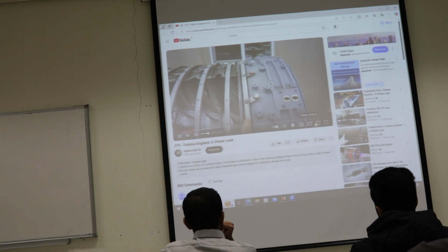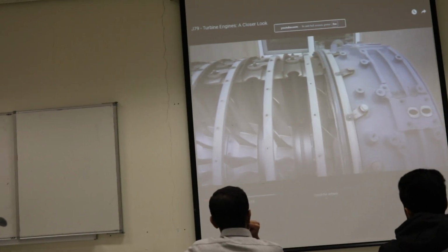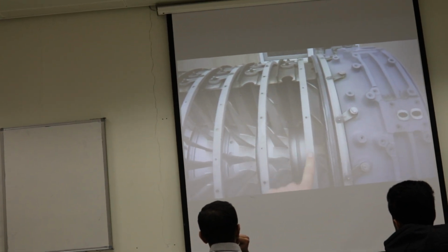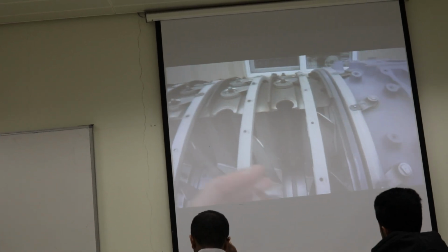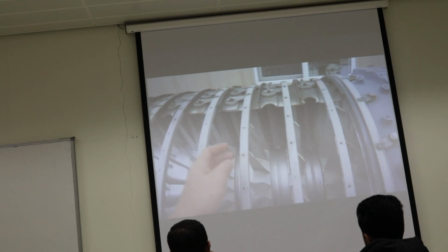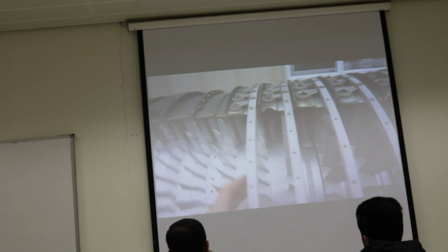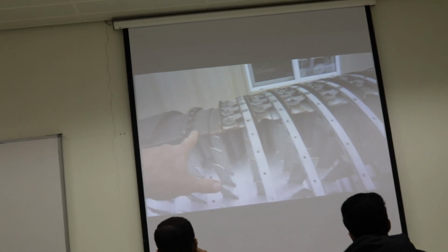These are the actuating rings, the VIGVs. Then the first stage of the compressor. What is this? Sorry, don't move. This is what? The actuating ring. Yes, this is a component of the engine. Stator ring. Second stage of the compressor. Second stage stators. Three. And down the line, stator four, followed by the moving blades. Each row of stators and moving blades is a stage.